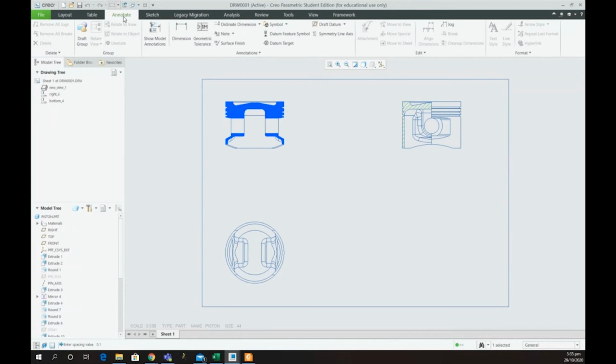But when you are moving forward, in real life, in your industry, tackling such complex parts, we create bigger drawings, not on A4, and also we create several views of each part, so each dimension can be tackled. I would just select the model and click on show model annotations. When I click on that, you would see there would be a hell of a lot of dimensions.